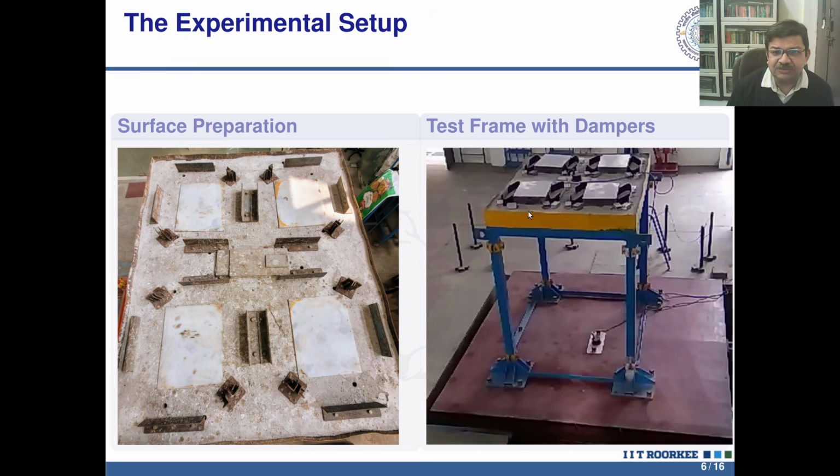And the whole idea is that this single mass block can work as a damper, or the auxiliary mass works in both directions. We can place springs here also, we can place springs here also. So one mass block effectively takes care of vibration in both the horizontal directions without any problem.